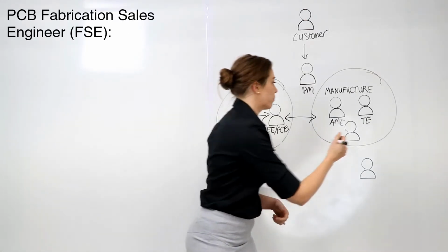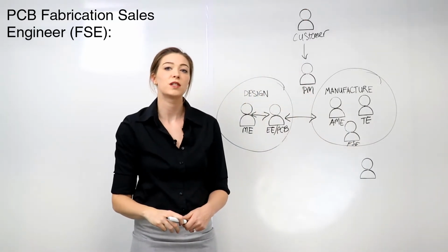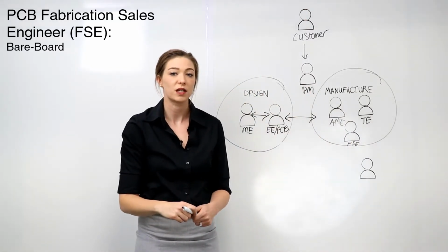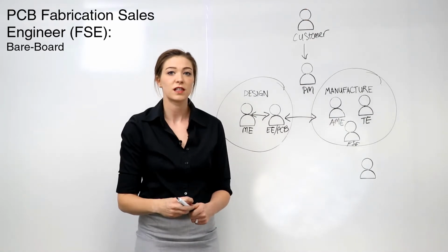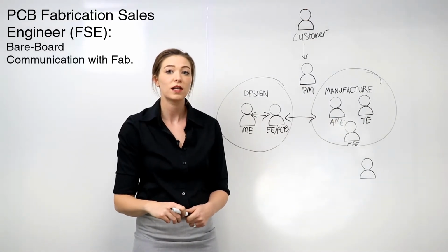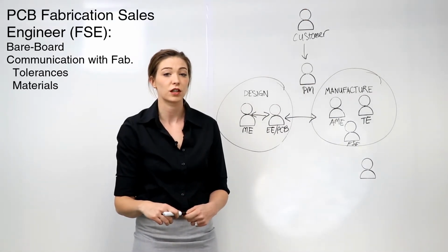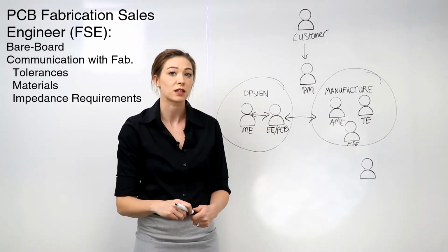The FSE is responsible for obtaining the required bare board for the PCB assembly. They will also facilitate communication between the design team and the fabrication house. This will allow them to answer any technical questions regarding manufacturing tolerances, materials, or meeting impedance requirements.